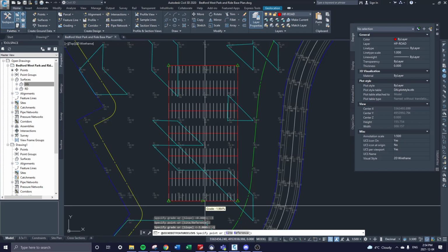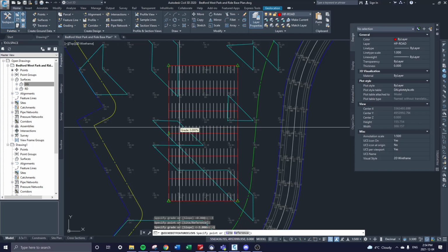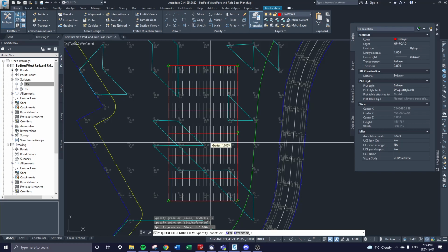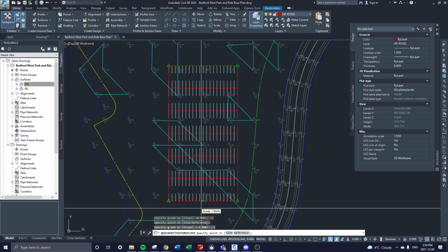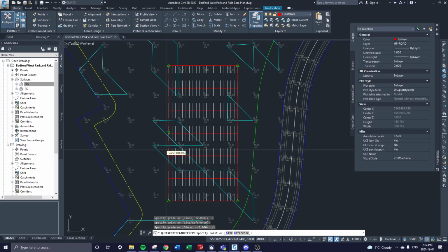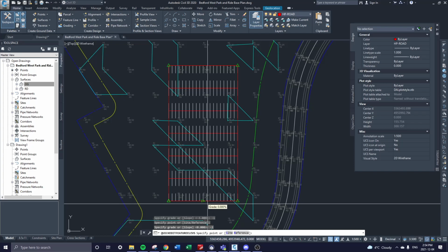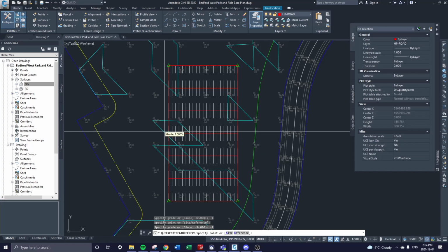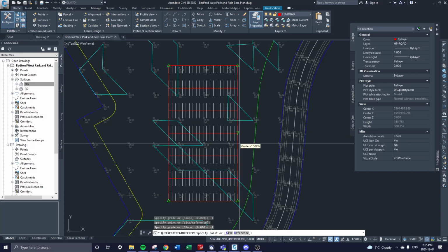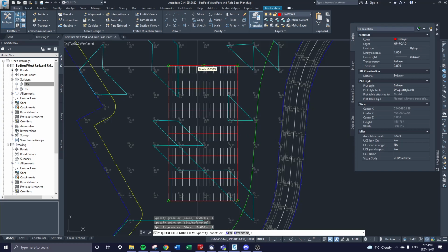That seems reasonable. Okay. And for your parking lot, we can't have a grade less than 1%, and we can't have grades greater than 5%. So let's see, that goes up at about 2. That's at 0. So we should probably put that at -1 as well. That's at 0. Well, that's a bummer. We don't want that. So maybe we'll make that at -1%. That's going to change this grade. So that's at -1%. That's at -1.5%. This one's also going to be at 0. So maybe we'll have to make that at -1% too.